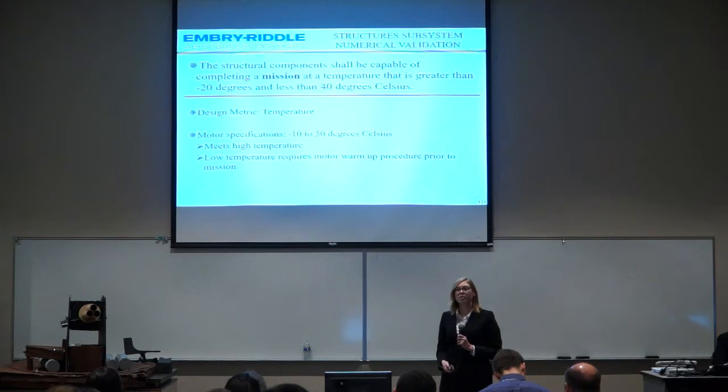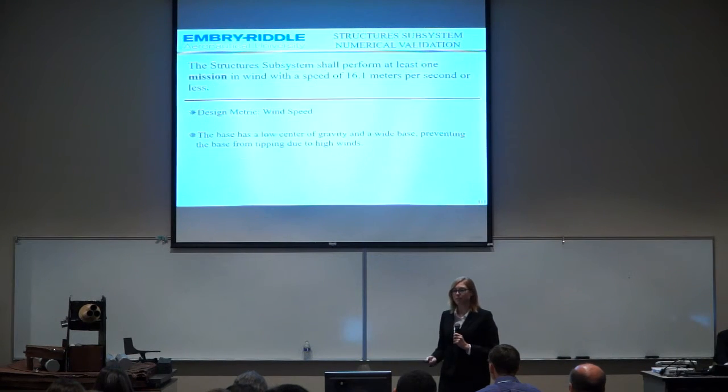Next, we looked at our motors. Our motors are specified to run in temperatures between -10 and 50 degrees Celsius. While this meets our upper bound for temperature, it does not meet our lower requirement of -20 degrees Celsius. Therefore, before performing any mission in temperatures colder than -10 degrees Celsius, our motors will need to go through a warm-up procedure prior to the start of the mission.